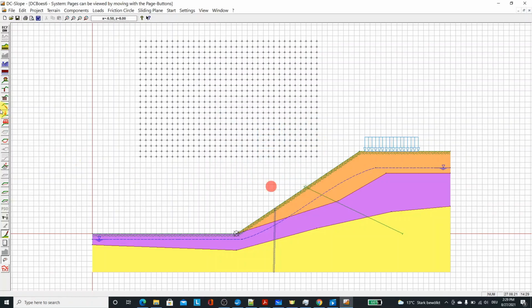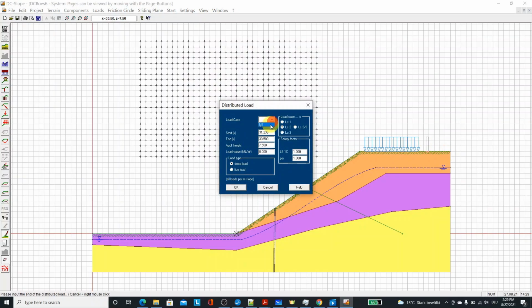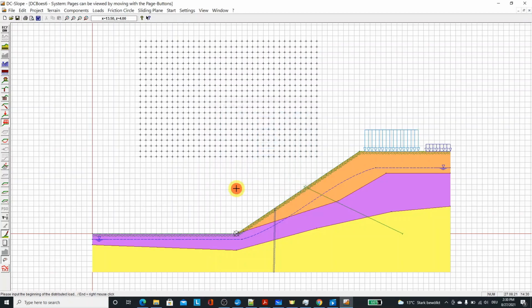Then I can also define additional loads here. I cancel this one and define additional loads. I will click here and click here, and it can be in the same group as the live load, but this time I have a dead load and the amount is probably a little bit less. Then I can define it this way. And now I have defined additional loads. If I start the analysis, this live load will be considered if it's unfavorable. The dead load will always be considered. And now I have my result, which is the same as this circle here.